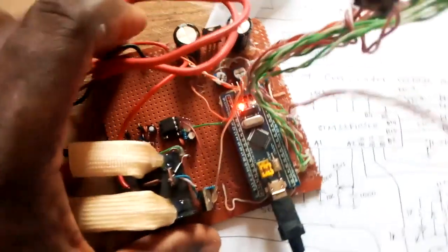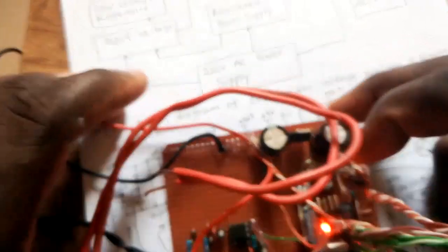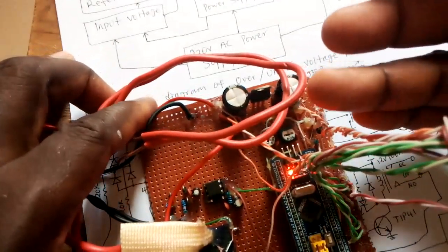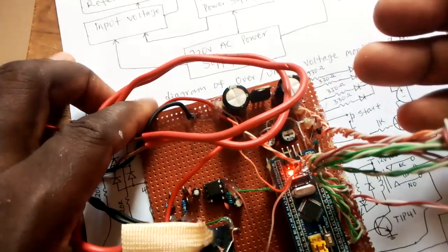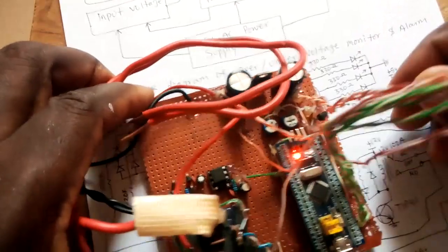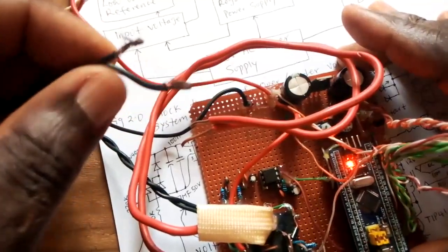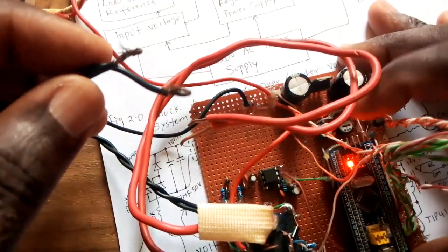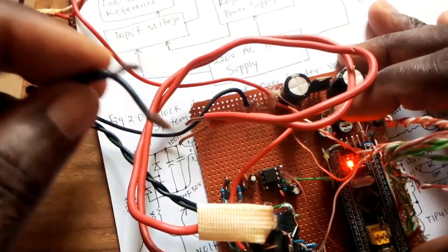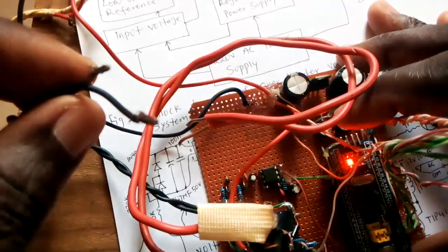Although I've tested the system and calibrated it, you need to have some sort of equipment in your lab, a variac. I have a variac that I made, whereby you should be able to have like an 80 to 400 volt AC variable source, which you are going to use. But if you don't have that, if you have a small generator, you can increase the voltage to adjust this, because you'll be increasing the voltage, reducing it, and then connecting your multimeter to set this. So you see, it's very technical to be able to set this thing up to that range.